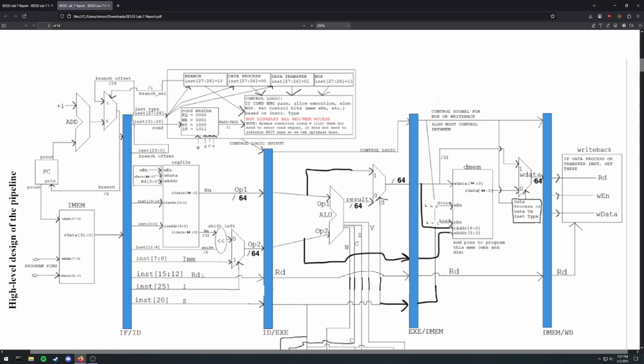This is our stage register, and that decomposes the instruction from the IMEM into the bit fields referenced by our ARM architecture. We access the reg file using rs. Some other bit fields are taken out, like the immediate I flag, S flag, and the destination register, which gets passed along the whole pipeline.